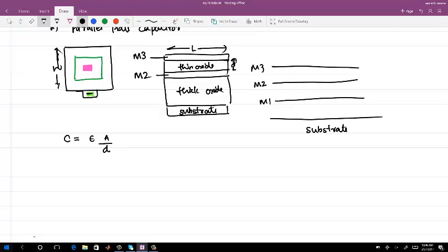And can you have now, I think in 65 nanometer technology, you have some layer in between the two metal layers to realize the capacitance. I think if you look at MIMCAP, that part. These metal layers are designed for all the contacts and other things. But if I want to have a better capacitance than what the thickness is provided by these metal layers, I need to reduce the oxide thickness, and I can't reduce the oxide thickness with these metal layers. They are fixed.